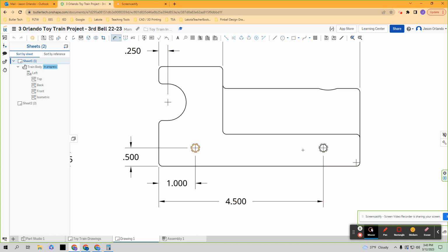Right, now we know that these two axle holes actually have the same height. If I just give that one dimension, it's not very clear because there's a whole lot of distance in between them. So I would maybe need to also dimension the height of this one, but I'll give you another trick. What if I get the height dimension of this one, but drag it intentionally across the part over here?